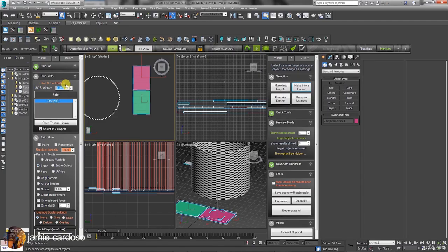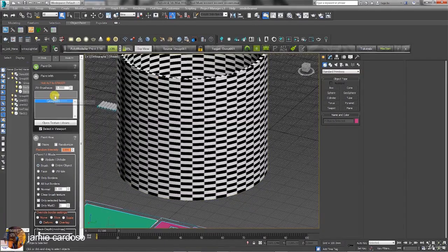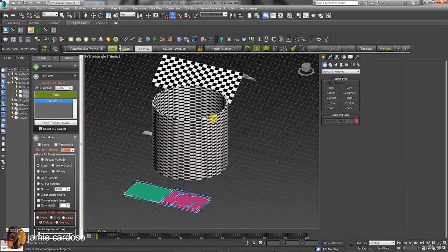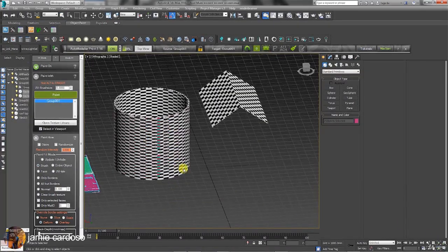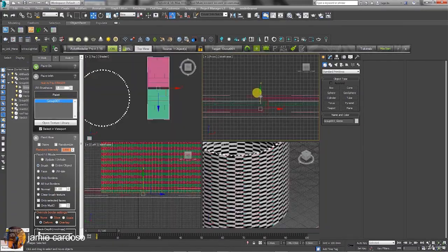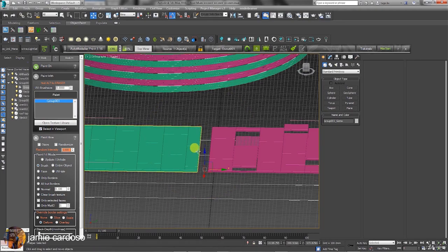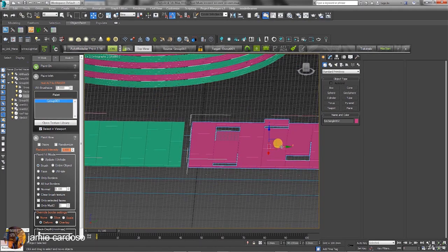Change the brush size to 5. Enable the deform function again. Close the Properties dialog. Enable the paint button again and begin painting the new mesh sources. As previously done, let's adjust the gizmo. This gap is what we currently have between these separate surfaces. We can move them closer together to bridge the gap.